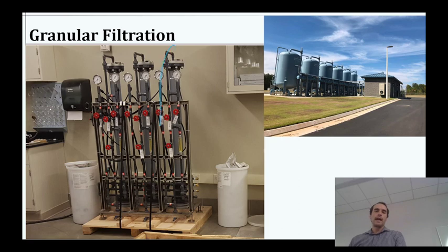I've actually got some of these in my lab. These are just kind of a pilot scale granular media systems where we can put a little bit of pressure. The columns themselves, keeping it like a tall, thin cylinder, keeps the sand grains a little better compact and can handle more pressure than if you just leave them as an open bed. The problem with the open bed, if we put too much pressure, eventually the sand will just get pushed aside and you'll get a fissure and water will just go straight through, and then that's a problem because then you're not treating the water. So it gives a little more pressure potential, and if anybody's interested, I could walk you over to my lab at some point, kind of show you how those go.